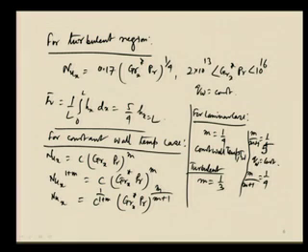So, for two different cases that power is going to change. For the laminar case, for the constant wall temperature condition it was 1 by 4, and now here it is becoming 1 by 5. For the turbulent situation it was 1 by 3, and here it is becoming 1 by 4.